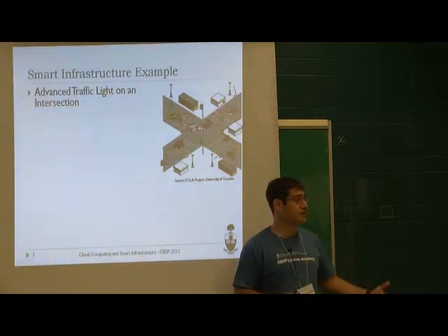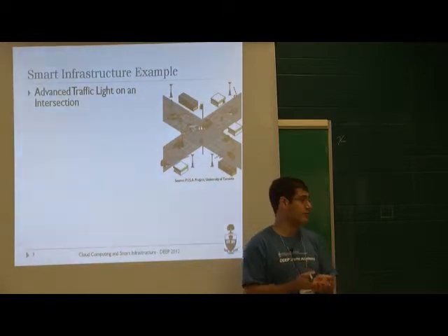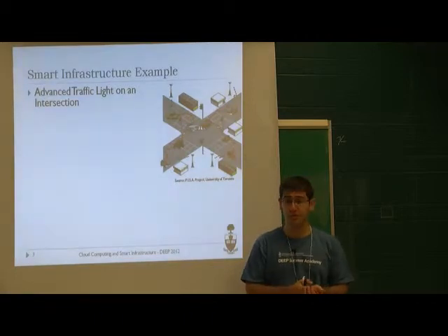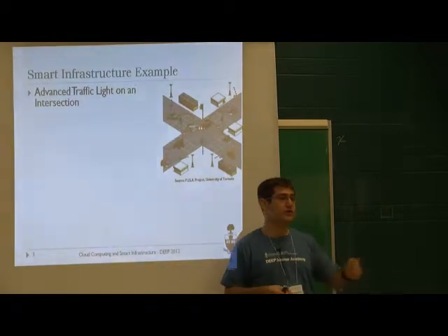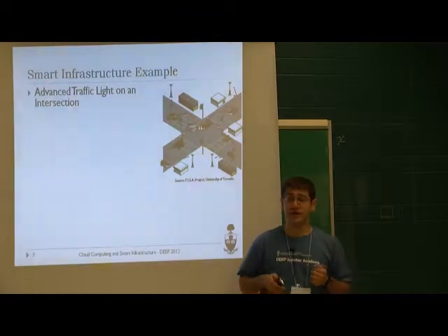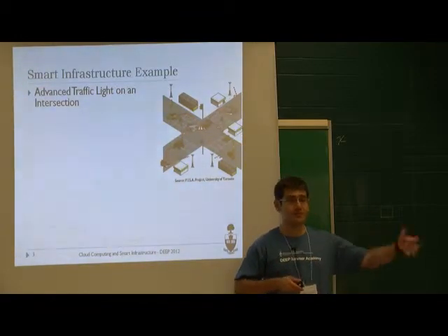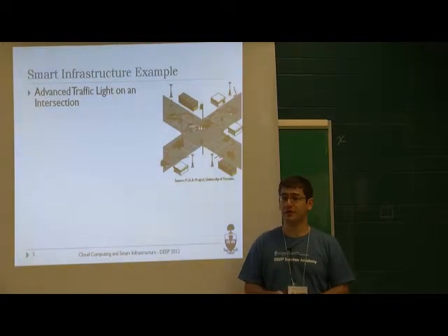Whenever pedestrians are crossing the major road, the major road has to stop, right? They have to have a red light. For the red light to appear, you either have to have your cycle ending, or you can use the pedestrian push button, right?